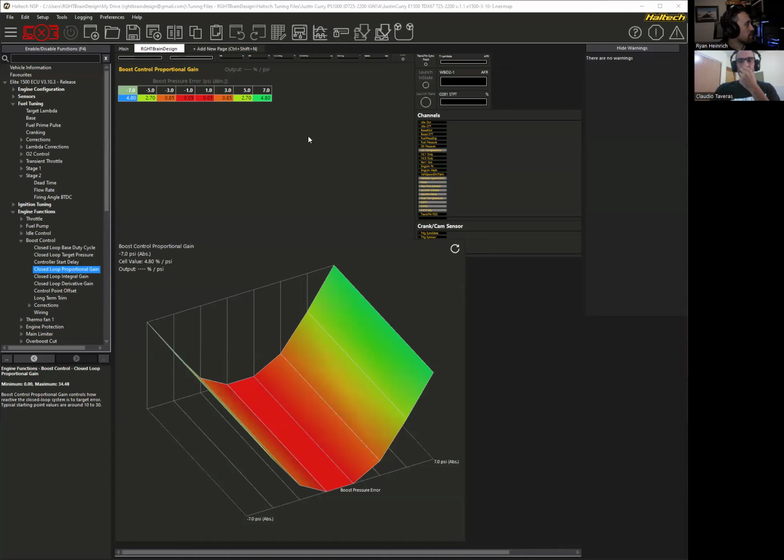This is one of the boost PIDs that I use pretty commonly. When we have our error, the boost controller is pretty much shut off. So 1 psi of error, don't do anything. Close enough, use the open loop table off of what we had calibrated in our initial lookup position table. And then when we are far away, that's when you're activating.